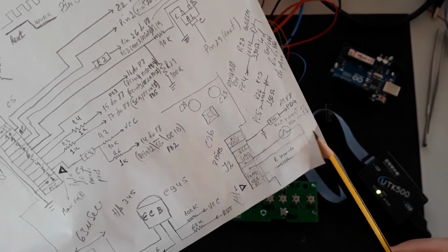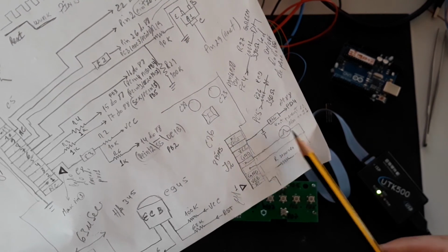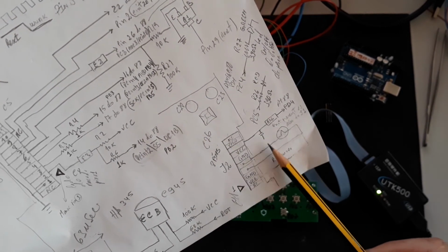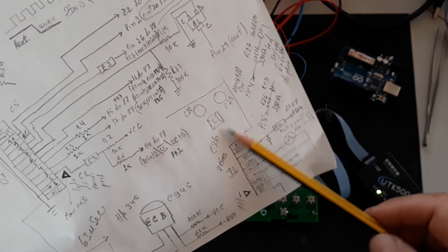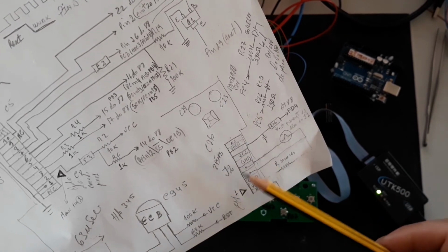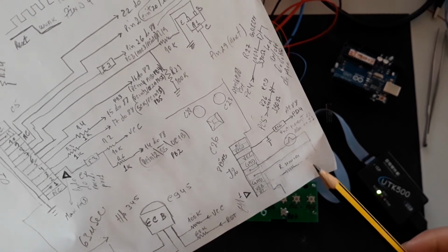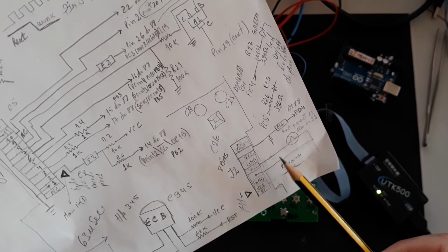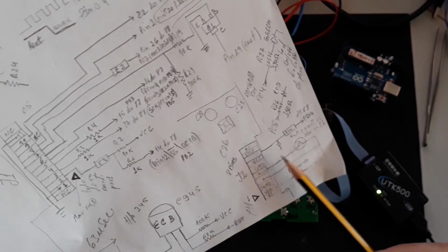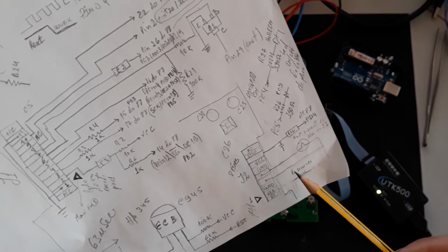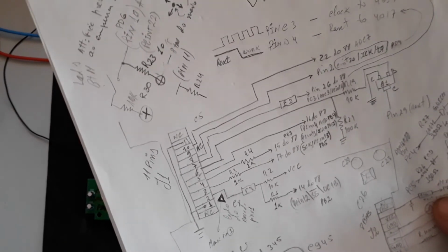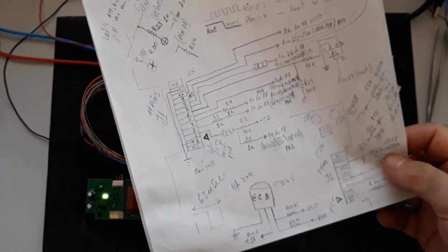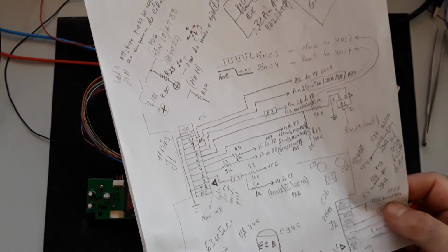I remember, to polarize the filament, you can use the 5 volts power and insert in series with the filament 2 or 3 diodes 1N4004, okay? Because each diode will drop 0.7 volts. This is a way to power it up, but the power source must be independent, okay?